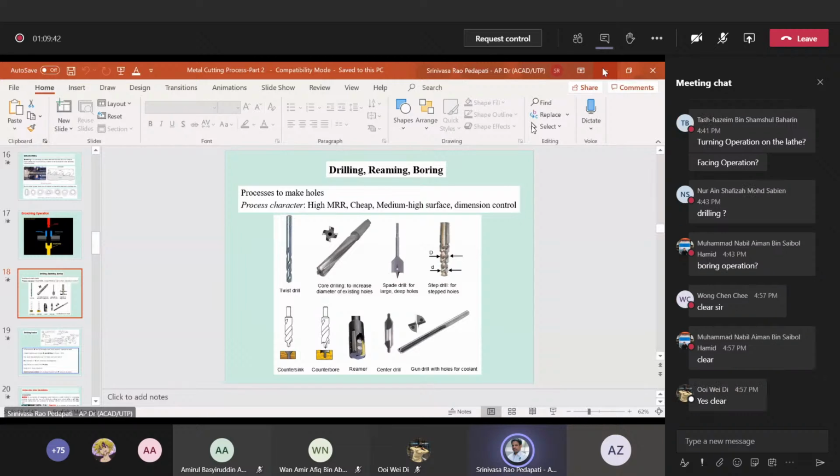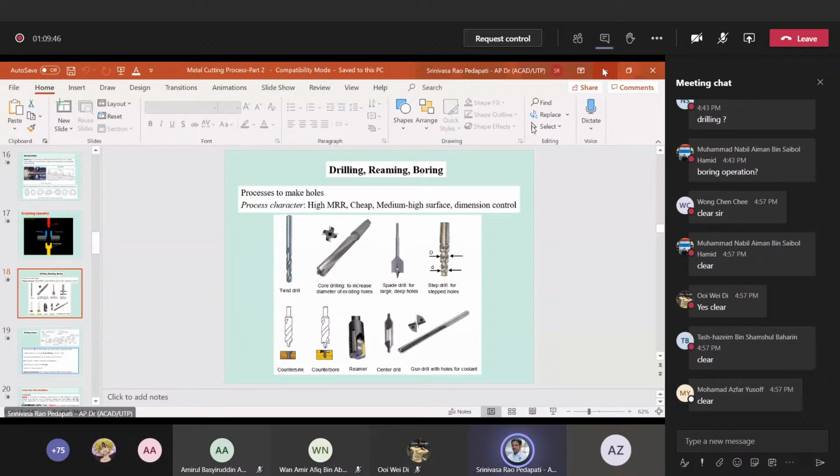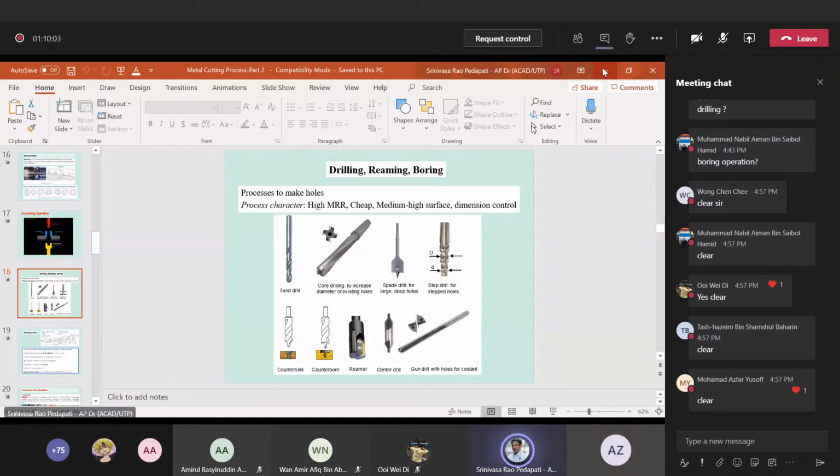Broaching, I think you can now appreciate, is actually a specialized operation. Here the cutting tool is expensive, because the cutting tool is very lengthy, and with so much gradual increase in cut, preparing a cutting tool is difficult in this process. Getting the tool is expensive, but the operation performance is very easy. Just you have the tool, you run it, finish.